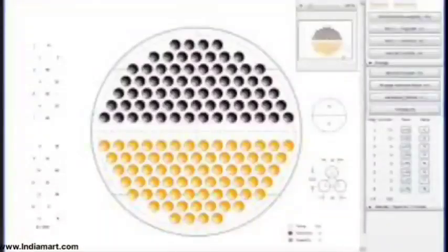As for the first question, tube sheet thickness: by PV Elite, whatever inputs are there, you put them in and you will get the output from there. The second one is the thickness of the fillet. Normally, for the fillet we take 0.7 of the minimum thickness of whichever parts you are welding. And as Ramkesh told, if you refer to UW.